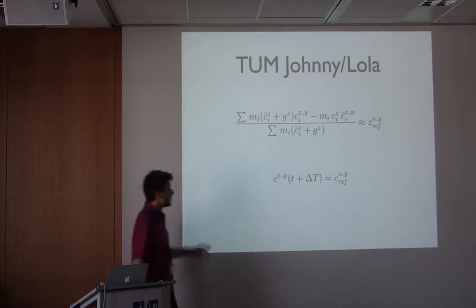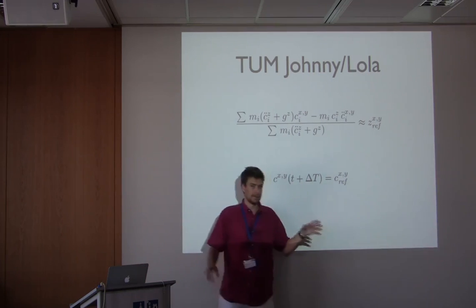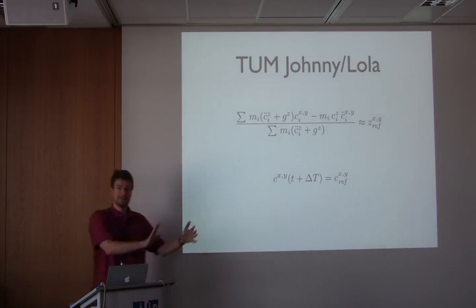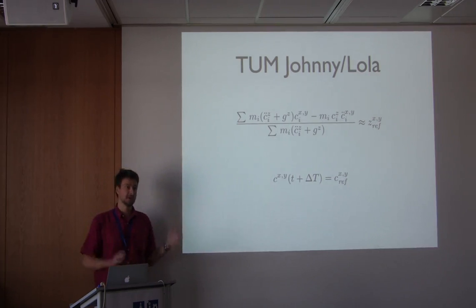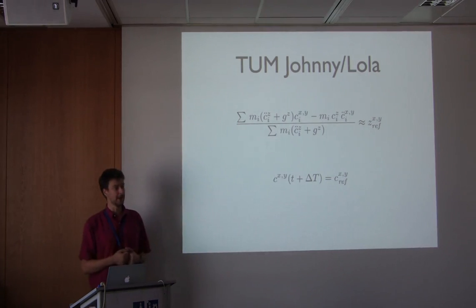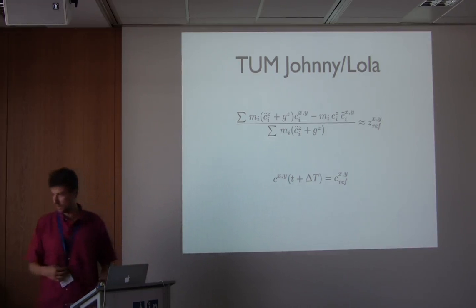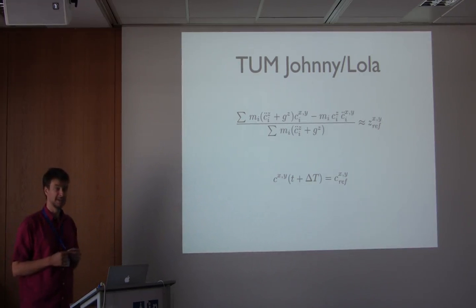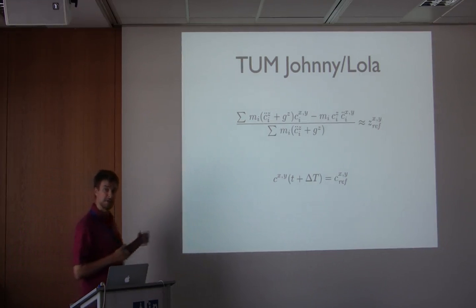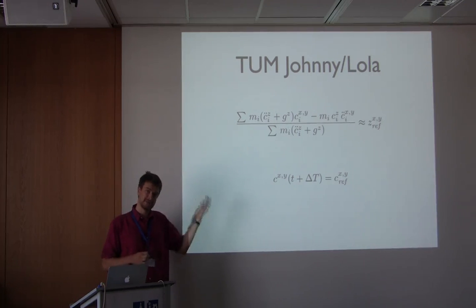Okay. So here they impose the position of the center of mass for some time and not speed. So capturability is not constrained. So in some way, there's a failure here in applying proper theory. Hopefully, systems are robust to design errors, so it works. But regarding the theory, there's a failure here.